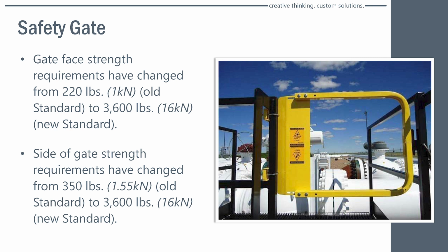I do like the safety gates that close, okay? And the gate face strength requirements have changed from 220 pounds to 3,600 pounds. You go, how in the world do we do that, Ronnie? Well, think about the locking mechanism. That's the key. So when it swings back in, the locking mechanism is there. It really just stops you from being able to push it back open unless there's a lot more force applied against it. Very simple.